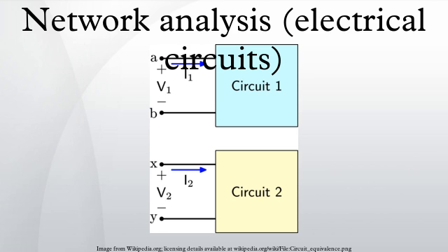There will always be dependent generators in a 2-port parameter equivalent circuit. This applies to the H parameters as well as to the Z and any other kind. These dependencies must be preserved when developing the equations in a larger linear network analysis. Piecewise linear method. In this method, the transfer function of the nonlinear device is broken up into regions. Each of these regions is approximated by a straight line.